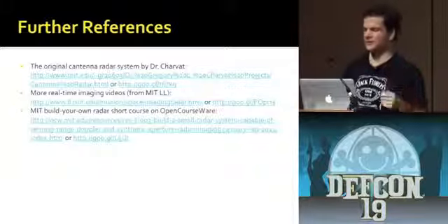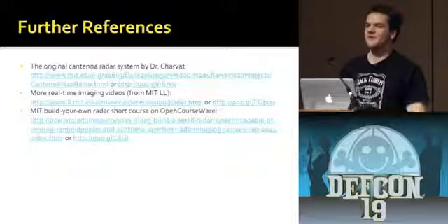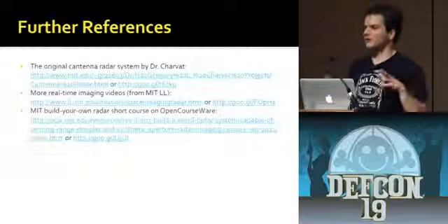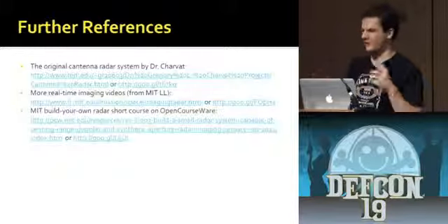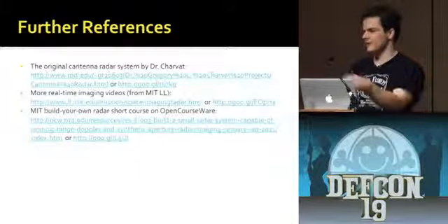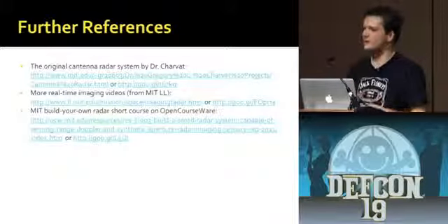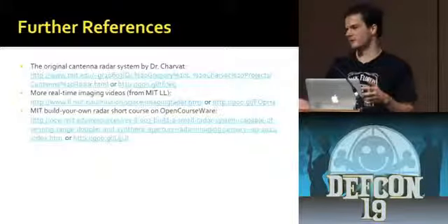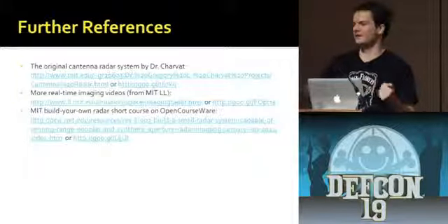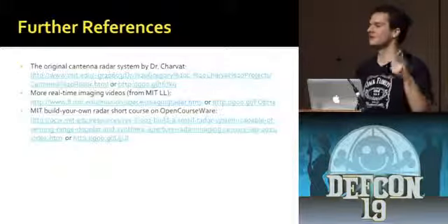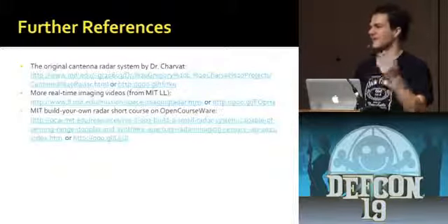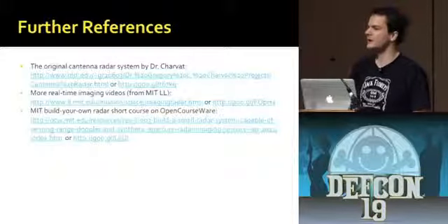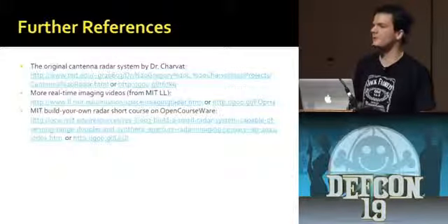He asked if I was looking at software-defined radio systems. I think there would be some benefit to that, certainly for the SAR coherent processing stuff. That would benefit greatly from an FPGA system because it can take a few seconds to process an image like that on the computer. But in this case, the main goal is simplicity and low cost. So if you bring in one of those research boards like the USRP, that's going to add a big chunk of change to your design. But there's definitely a lot of potential there. I would say that's absolutely worth exploring.